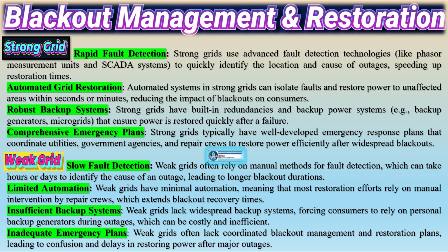Strong grids use advanced load forecasting tools that rely on machine learning, big data, and real-time analytics to predict demand and ensure that the grid is adequately prepared to meet changing loads. Strong grids implement DSM programs that encourage consumers to reduce their energy consumption during peak hours, helping to balance supply and demand and reduce strain on the grid. Real-time demand response programs allow strong grids to adjust demand in real time by offering incentives to consumers to reduce usage during peak periods, improving grid stability and reducing the need for peaker plants. Strong grids often have widespread smart meter deployment, enabling utilities to gather detailed usage data and enhance demand management capabilities.